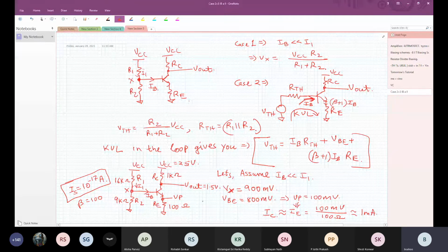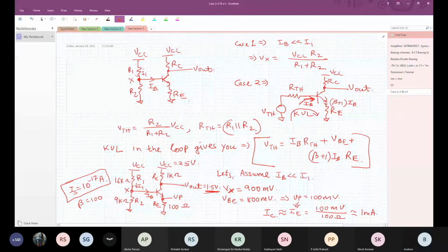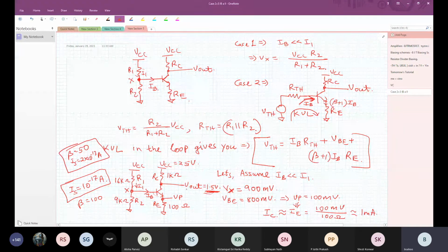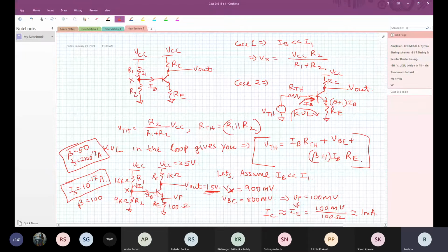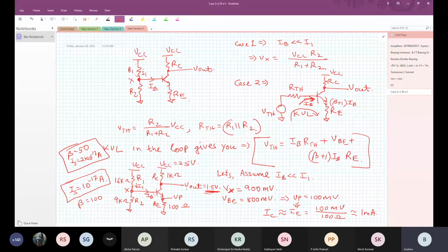Once he does that, he tells the whole class and makes a good business out of this and makes a ton of money. So Subhadeep, you are going to get richer. Now prove that when you change this transistor with a beta of 50 and IS equal to 2 into 10 to the power minus 17 amperes, this node budges very little from 1.5 volts. Prove it now. Please do that, because that's how all these demos work, when Intel and others come up with demos, they prove that things work like this.